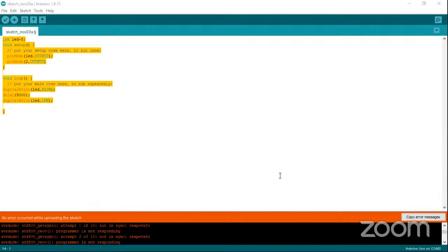Can we declare all LED pin numbers in one pinMode statement? No, that's not advisable. We should not do that. We would need to create an array, but arrays in C programming are a complex structure for us, so we won't prefer that. We will declare separately, this pin with this mode, that pin with that mode.